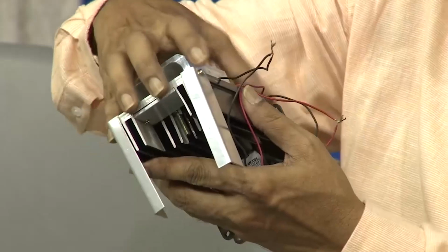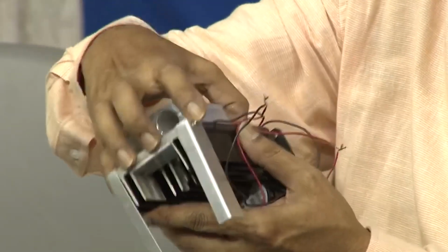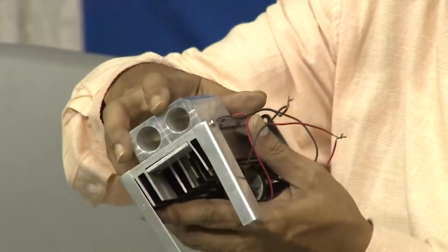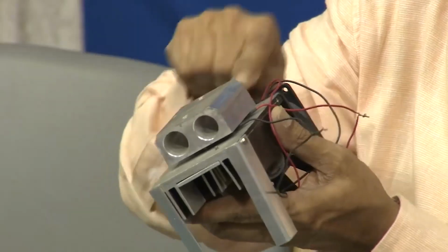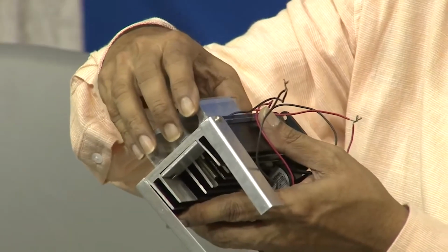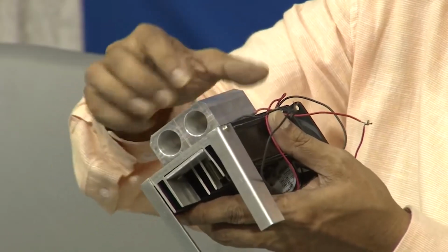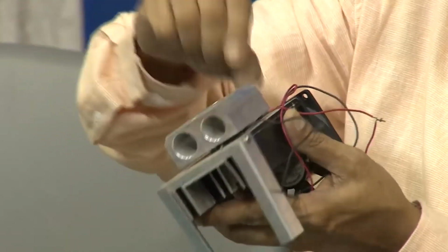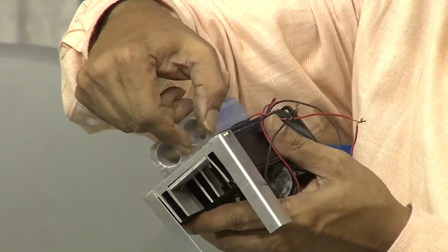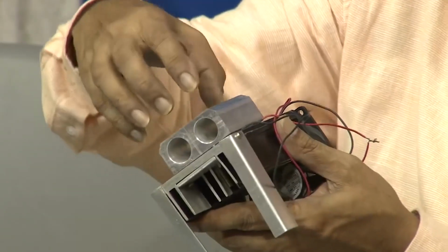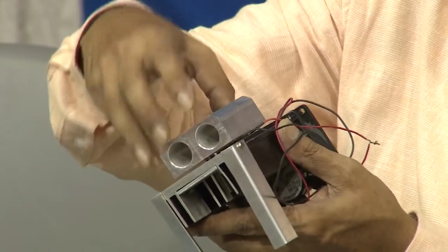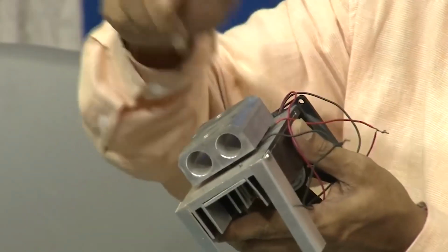So, this whole thing has been made such that it has a cap which we close, or in critical applications we also use a polyurethane foaming arrangement. The moment you cool it, we have a small opening, and then you put in the sample. This mass has been calculated critically, for a given mass of liquid, typically with specific heat of 1, and this aluminum block. The moment you keep all this, we know the rate at which we can heat or cool the device.